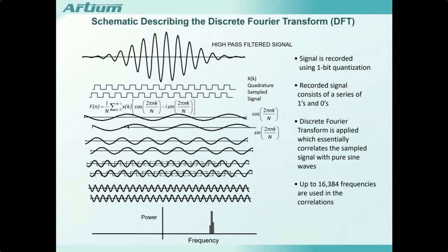If you had noise superimposed on this signal, we might have some other samples in between. That noise would not correlate very well with our sinusoidal approach here. And if we have noise, what you'll have is a distribution of the noise along the power spectrum, but with adequate signal, that noise will be well below the power in the peak frequency, or the signal frequency.